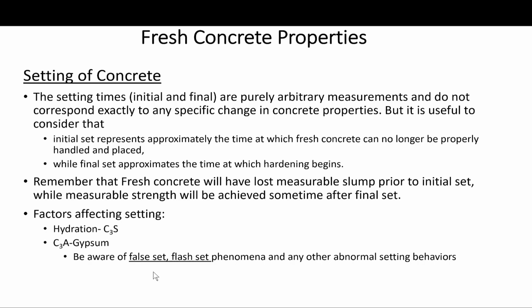Sometimes when the gypsum is interground with the clinker, the material in the grinding mill can get quite hot because of the high energy input during grinding. So the temperature can rise basically as high as 120 degrees Celsius, okay? Which will cause gypsum to partially dehydrate to calcium sulfate hemihydrate. You remember we talked about this. Gypsum is the dihydrate, and the other form of it is the hemihydrate or the plaster.